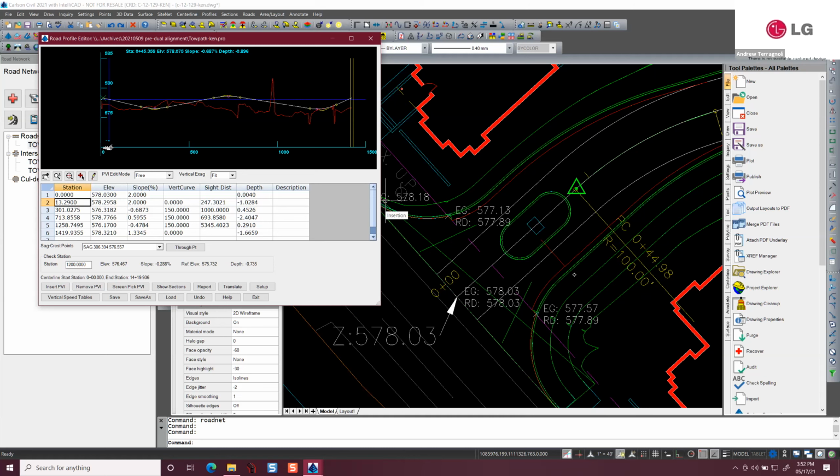So when you're coming down from the property, you say about 2% down, yeah. So you hit their edge of pavement. Now their edge of pavement's going to go 2% back up. So you're going to have edge of pavement act like a little gutter almost. That's exactly right. Remember, there's not going to be a ditch anymore. There's going to be a ditch up the road, but I'm filling in the ditch.